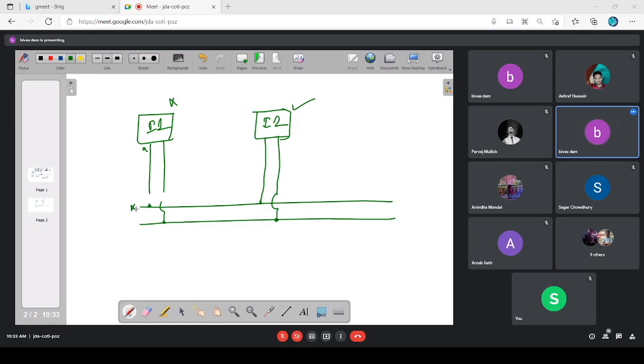So now there is a requirement that the output of one TTL totem-pole gate should have three states. One is the logic 0 state, one is the logic 1 state, and the third, new one, is the high impedance state. When the output is driven to the high impedance state, it is basically electrically isolated from the external world.